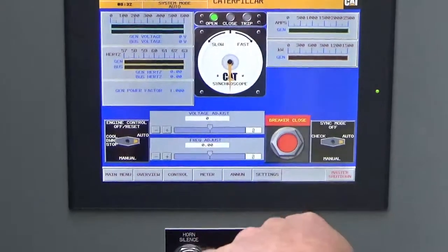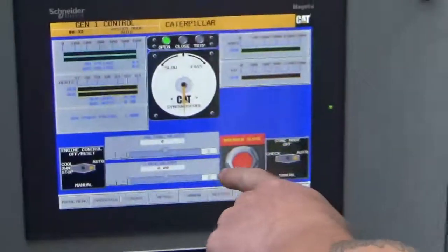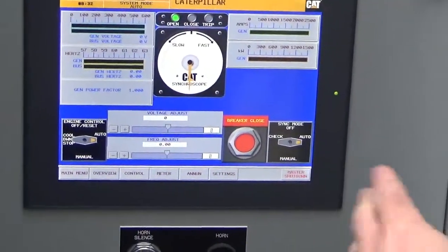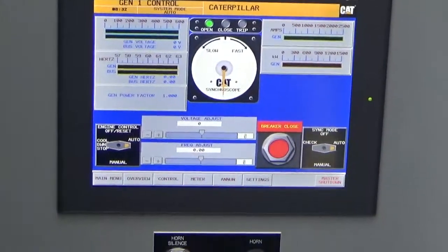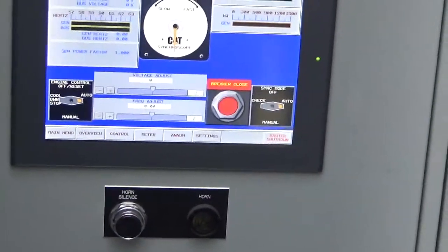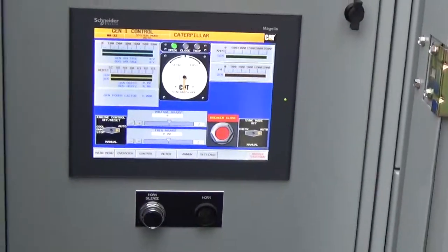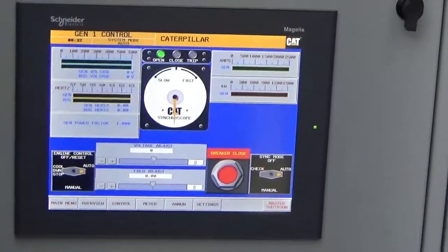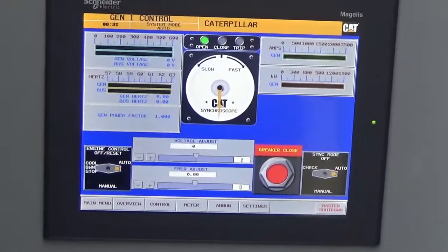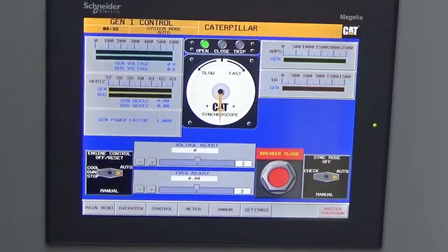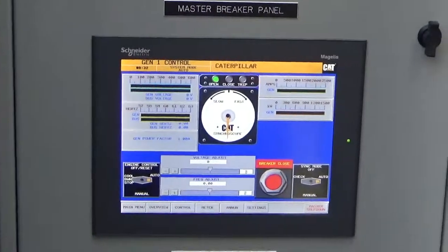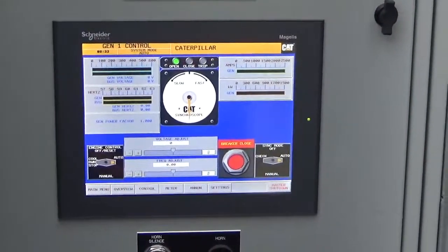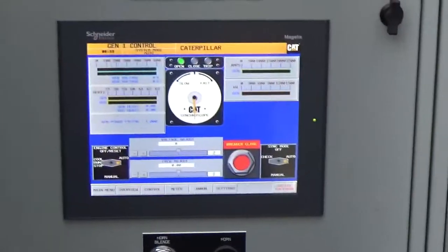And then when you adjust the bar, that number won't say 480 anymore. Most of the time with these, on the high side, we can adjust it up to about 500 to 510 volts. And on the low side, about another 30 volts. So what's that, about 450? About 450 volts. And with frequency, we normally are able to adjust it all the way up to about 64 hertz on the high side and about 56 hertz on the low side, if you go all the way.